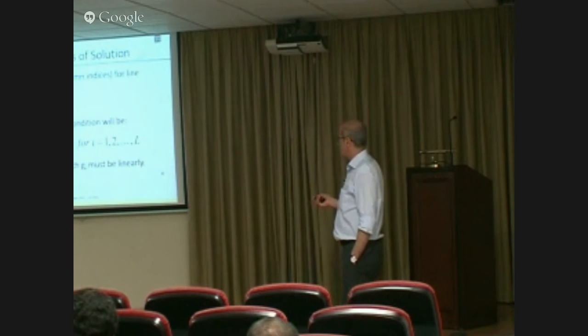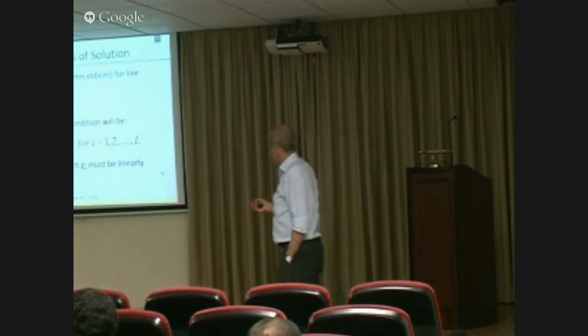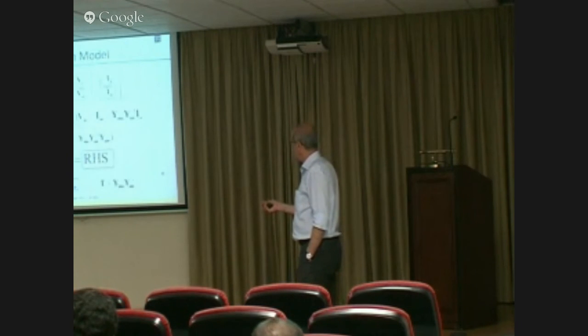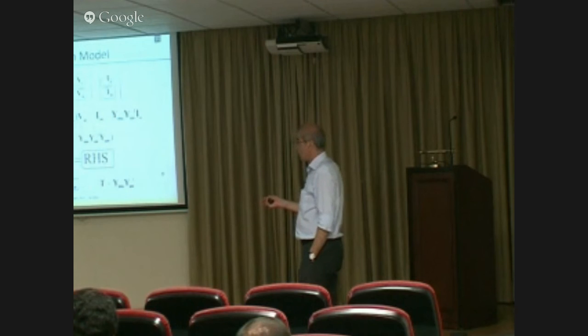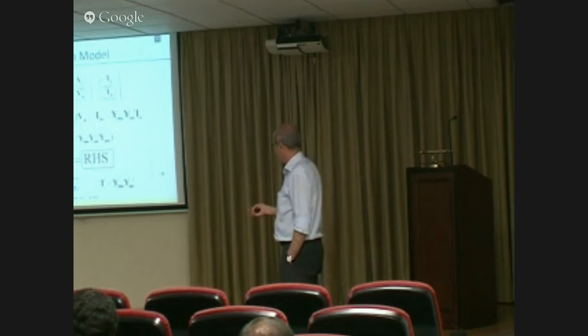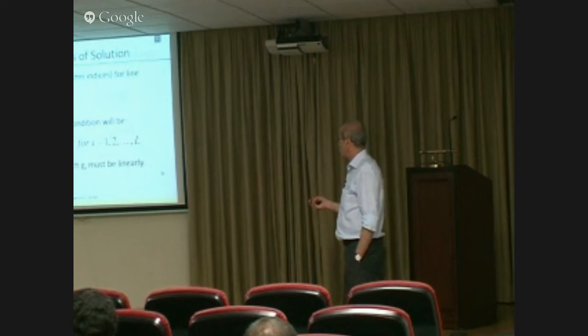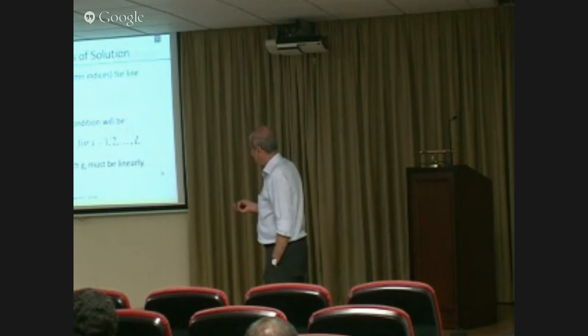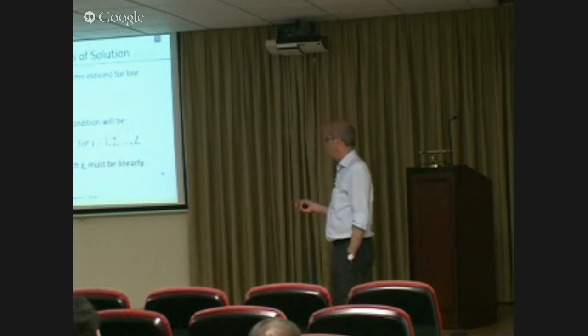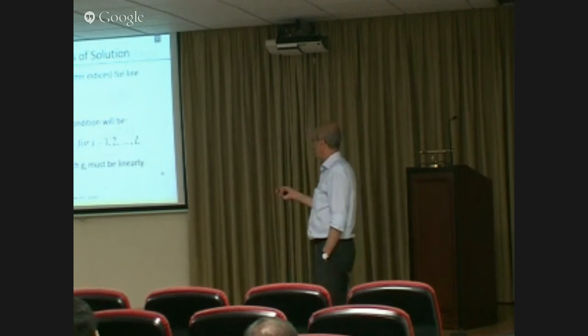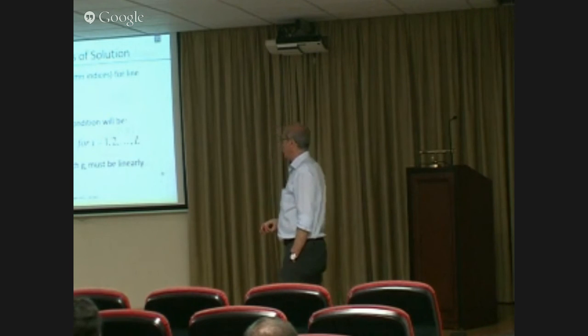Essentially, the uniqueness condition translates into finding the rank of this matrix T, corresponding to the buses which represent the terminals of this faulted line, and making sure that this set of columns in T corresponding to these terminals gives you full rank.